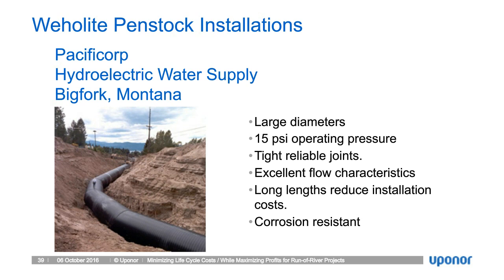And Black and Beach were the designers. There's a typo error there. The actual operating pressure is up to 8 psi. Tight, reliable joints, excellent flow characteristics, long lengths reduce the installation time, and very corrosion resistant. It actually replaced a wooden stave on this project.